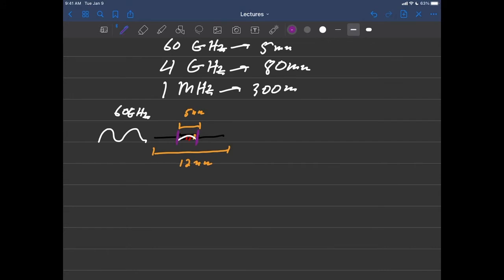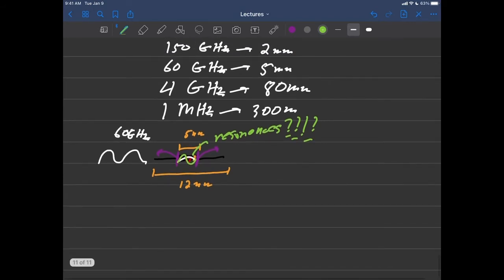And that could have some bad ramifications for your circuit, because as soon as you get a little resonating in there, you might get some energy going back towards the source, or some increased energy coming out the other way. Or you could even get a higher harmonic existing in there, maybe something like that second harmonic. It might just fit inside the resistor. These resonances can be bad, and they bring some question marks up. They might start introducing some undesirable effects in your circuit for reasons that would be difficult to diagnose. But it might very well boil down to the fact that you are choosing a frequency, say 60 gigahertz, that is just beginning to match some of the sizes of the components in your circuit.